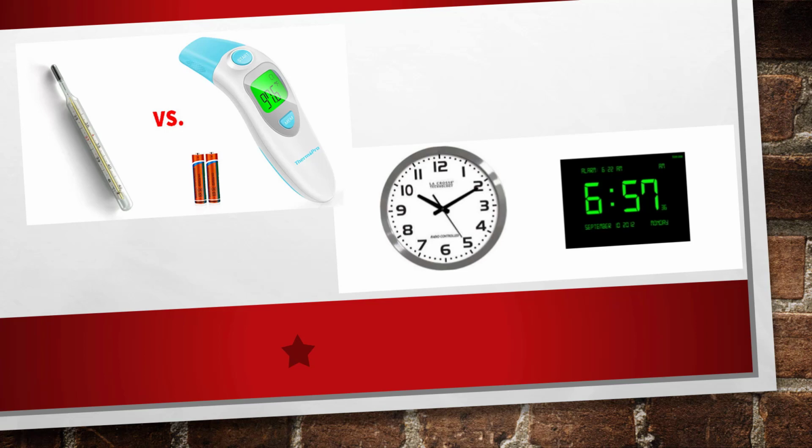Whereas if I use a digital thermometer, I'm going to see those values change in steps and increments. If it's 0.1 degree, 0.2 degrees, a half degree, I don't know. That's a feature of the precision of the particular instrument. But the point is, it's not going smoothly through all the points in between.